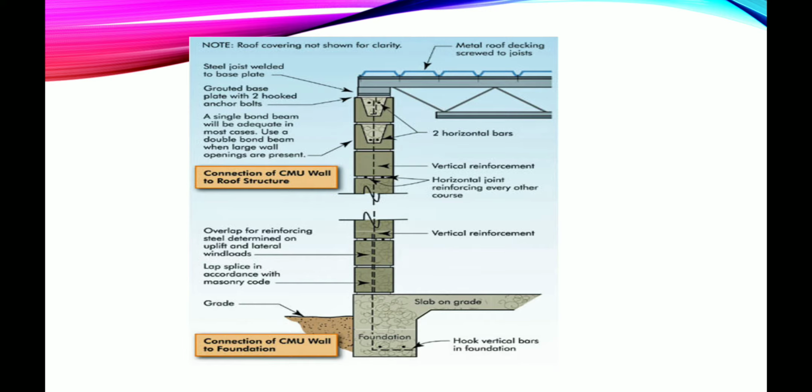Something to take into consideration is that connections are a key aspect of load path continuity between various structural and non-structural building elements. For example, consider a window. The glass must be strong enough to resist the applied load, and the glass must be adequately anchored to the window frame, the frame adequately anchored to the wall, the wall adequately anchored to the foundation, and the foundation adequately anchored to the ground. As loads increase, greater load capacity must be developed in the connections.